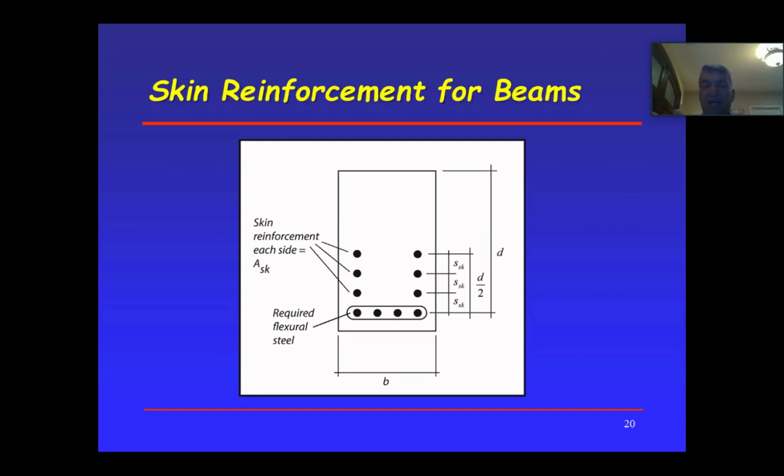So if my columns are 9 foot apart, that means the beams are 9 foot apart. That means the tributary width is 9 foot, 4.5 from this side, 4.5 from that side. That will give you reasonable dimensions for your columns and your beams. I just got off on a little tangent here. Okay, so that's usually the case. Now, so 9 feet on center.